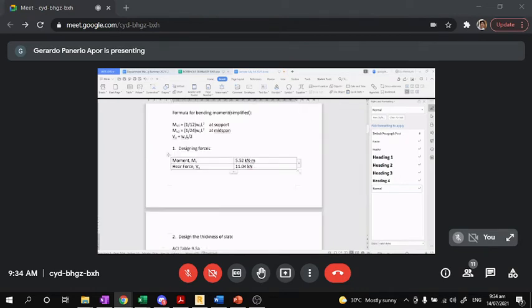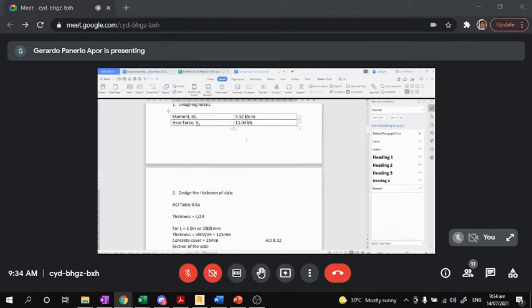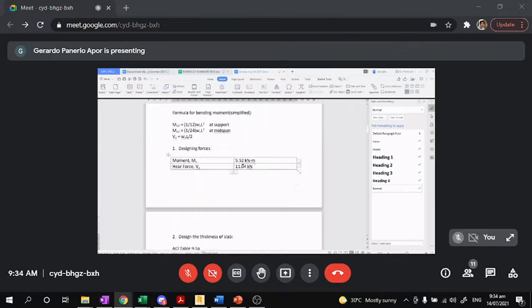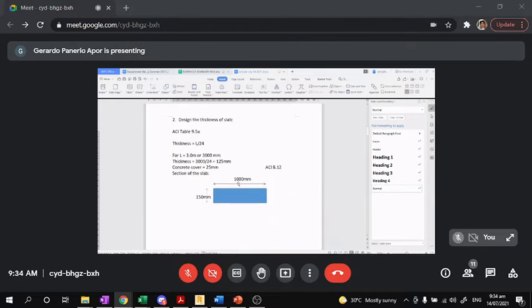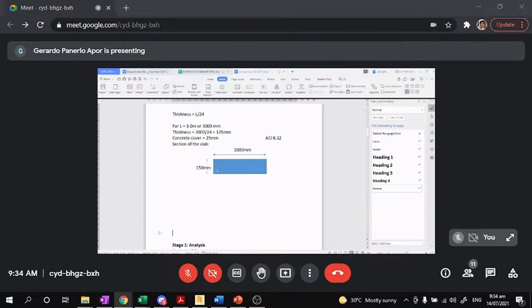Now, as for the reinforcement, that will be as follows. You have already a design force. For the thickness, there is a formula, unlike the beam where you can assume directly. This is similar to a beam, but remember the configuration is more of a wide width and a narrow depth. In a beam it is reversed, the width is usually narrower than the depth.